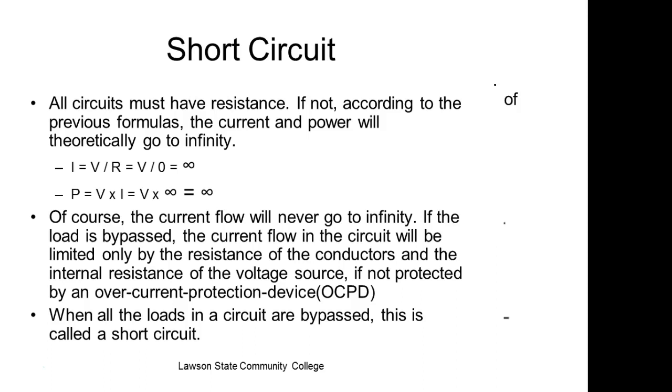Because it's rated at the current carrying capacity of your conductors. So if you put a 50 amp breaker on a 15 amp circuit, we'll be reading about your house on the news, especially if you're having that problem. We have people that do that. So now you've exceeded the current rating of your wiring. What you need to do is add another circuit, and move stuff off to another breaker. And those breakers aren't cheap, are they? Breakers are not cheap.